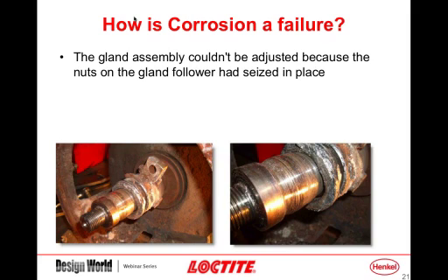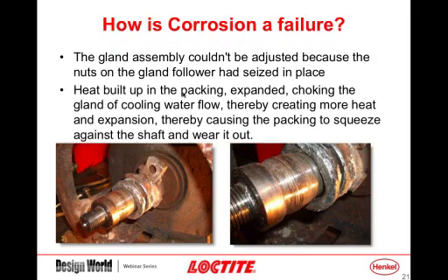But the reality of the situation was that the reason it wasn't adjusted so that you had a weepage, and you didn't get the shaft failure, was because the fasteners had actually corroded. So the mechanic who went in to do the maintenance was unable to make the proper adjustment, and therefore, since things weren't kept adjusted, you ultimately had a failure in that shaft, and then they had to be disassembled and taken apart.